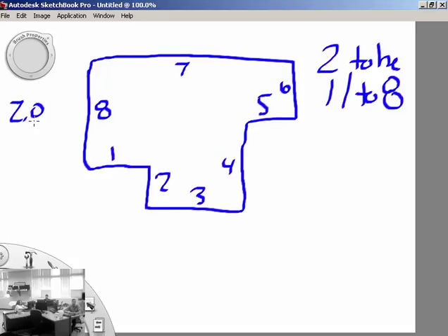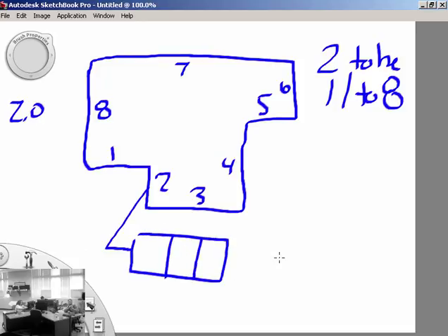I want you to put a feature control frame on this drawing that establishes that surface 2 is going to be parallel to surface 8. Do everything that needs to be done to establish this. Questions? All right, hop to it. There you go. There's your feature control frame and an arrow.